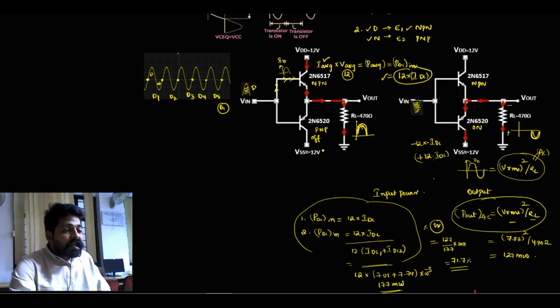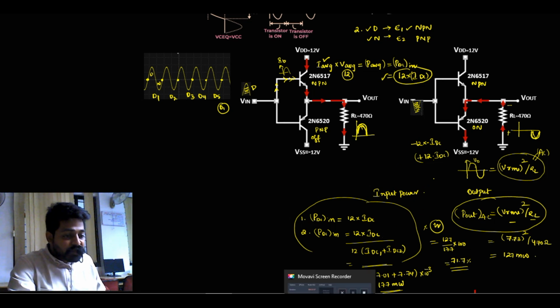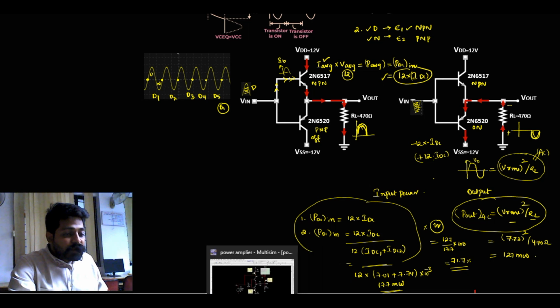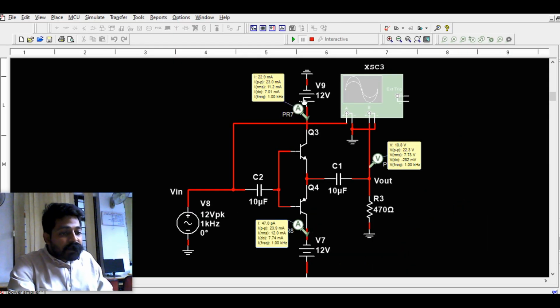We are expecting for the class B power amplifier, theoretically, the value of 74 or 78, which is calculated theoretically through the derivation in class. So we got this value when we did the practical simulations in Multisim. One more thing we have to observe is that when we give the VCC as the input, we are able to get the exact output waveform.